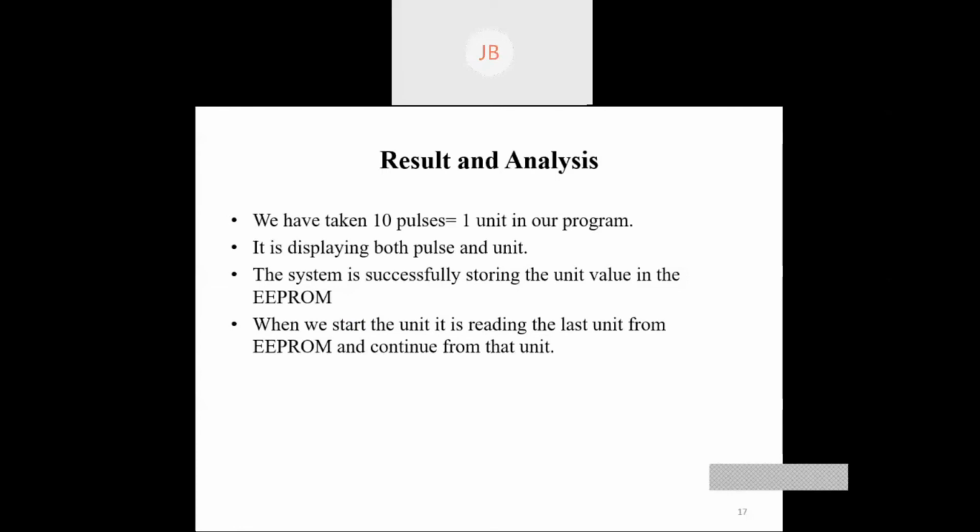We have taken 10 pulses equal to 1 unit in our program, and it is displaying both pulses and units. The system is successfully storing the unit value in the EEPROM. When we start the unit, it is reading the last unit from EEPROM and continuing from that unit.